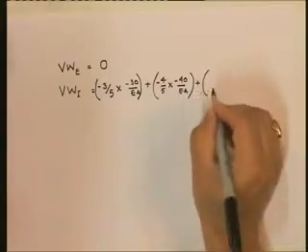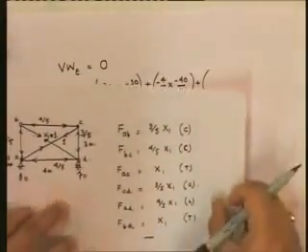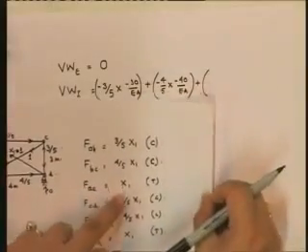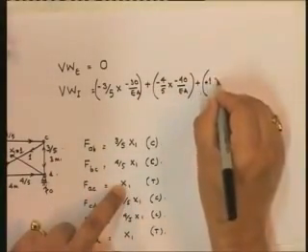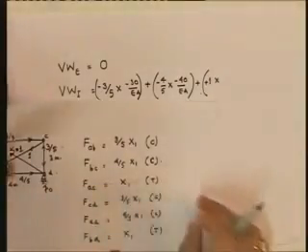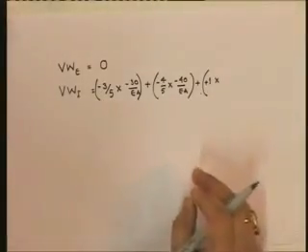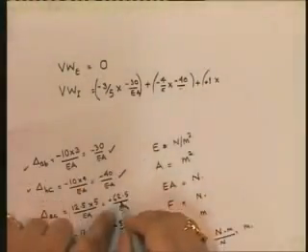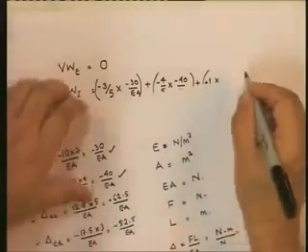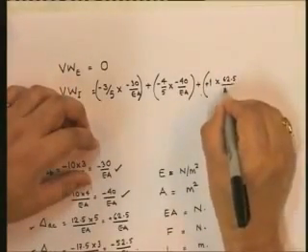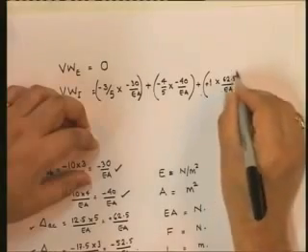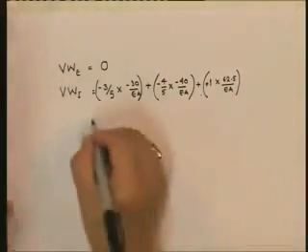Then I'm going to add what else? The next is AC. Force, tension 1. So it's going to be plus 1 multiplied by the real deformation in AC, which is plus 62.5 upon EA. That is member AC. Let us look at CD.